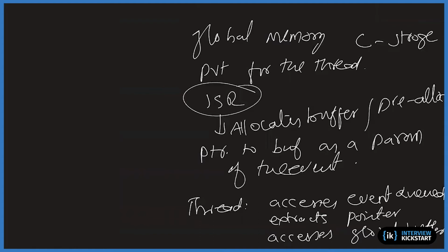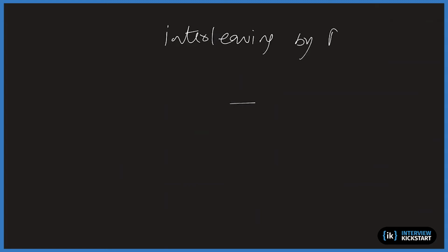Now, all these are non-blocking. Basically, it can proceed happily without worrying about other threads. The only thing that interleaves the threads is that if some other thread similarly gets a data event and wants to execute, it is the relative priority that decides. So the interleaving is not avoidable in preemptive priority scheduling.